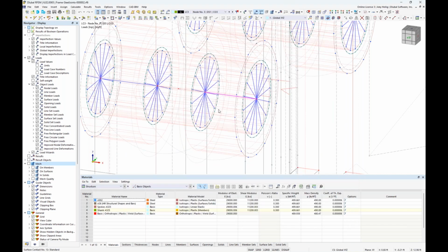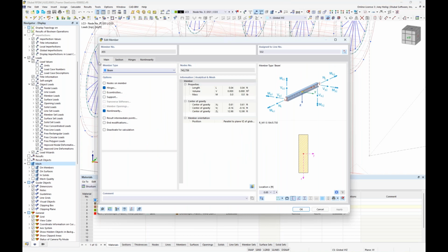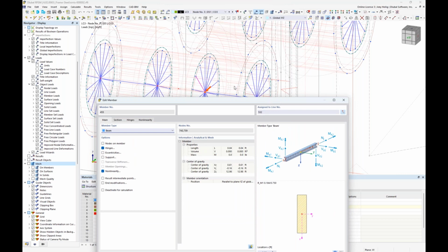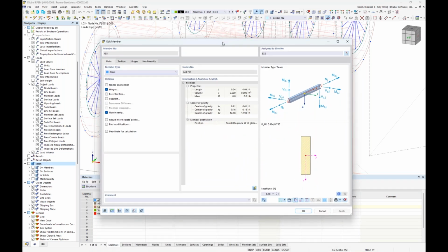And we are going to transfer the forces in this opening where the bolt is passing through with what we call these spoke members. And these spoke members are nothing more than beam elements themselves with a cross section assigned, and everything is optimized here with the cross section and the number of spoke members in order to transfer those forces between the plate element to the bolt and vice versa.